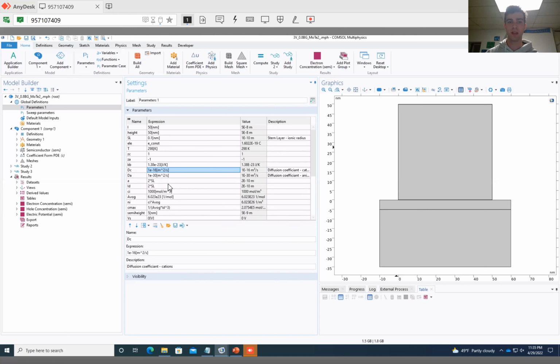We don't tend to care about dynamics with the studies that I've worked on. But you can tune this to adjust to whatever experimental diffusivity you can come up with in the lab. Our anions are set to an extremely low value, especially relative to the cations right now, of 10^-30, which basically means they're frozen. And that's what we want for an ionomer. We want only one of the ions to be able to move, in this case, the cations. We want the anions to be modeled as basically a solid polymer backbone that is able to move throughout this matrix.